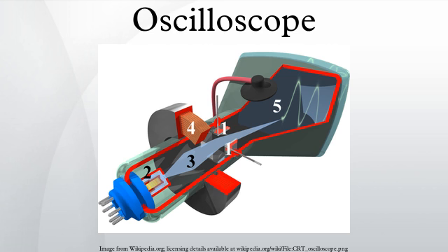Selection. For work at high frequencies and with fast digital signals, the bandwidth of the vertical amplifiers and sampling rate must be high enough. For general purpose use, a bandwidth of at least 100 MHz is usually satisfactory. A much lower bandwidth is sufficient for audio frequency applications only. A useful sweep range is from 1 second to 100 nanoseconds, with appropriate triggering and sweep delay. A well-designed, stable trigger circuit is required for a steady display. The chief benefit of a quality oscilloscope is the quality of the trigger circuit.